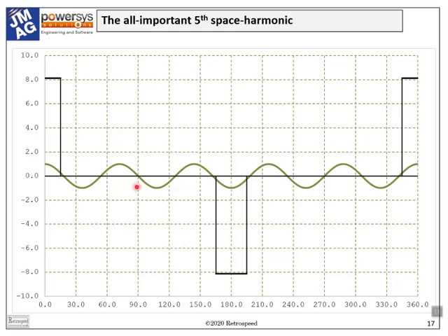Are these not just a figment of the mathematician's imagination? In fact, we need the fifth harmonic MMF components from all three phases, because the fifth harmonic wave from one phase alone is stationary in space, merely pulsating in synchronism with its alternating current. It's only when we put all three phases together with a three-phase set of sine wave currents that we get a rotating fifth harmonic component.